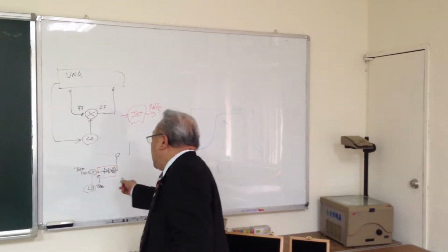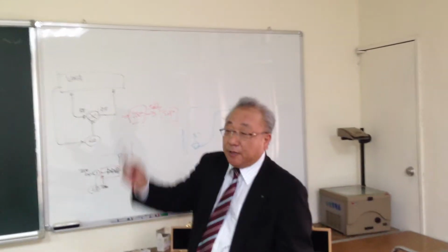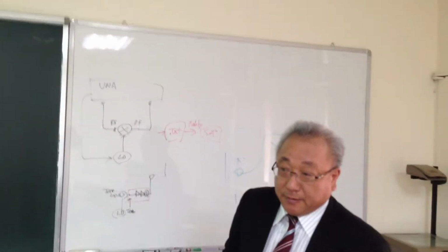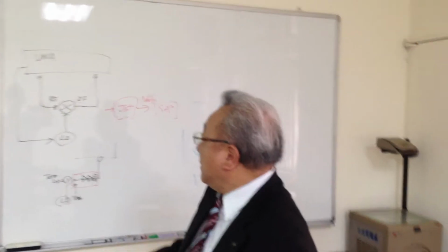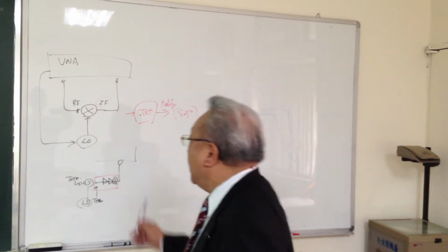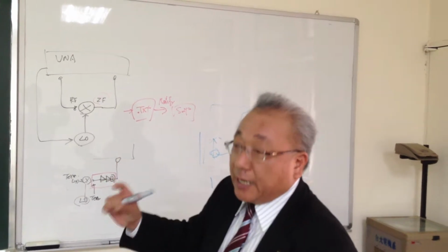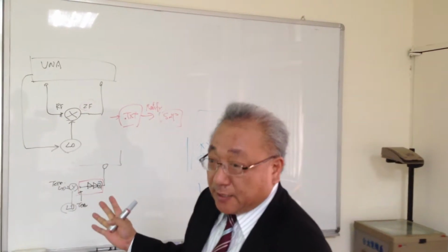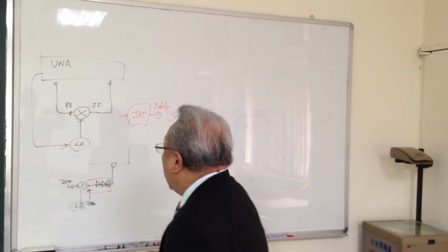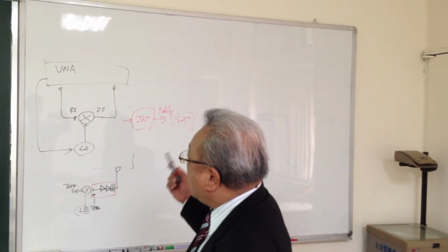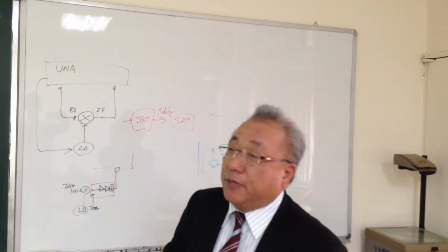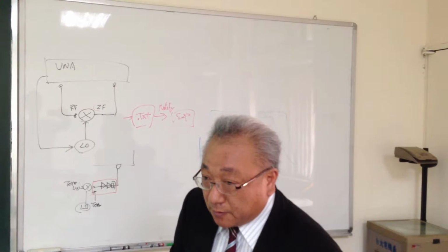Then you can choose the filter, which is only a low pass filter. So it's easier to construct the composite receiver, I think, because the IF is sometimes not so wide. And the measurement process is the same as the standard noise figure measurement.